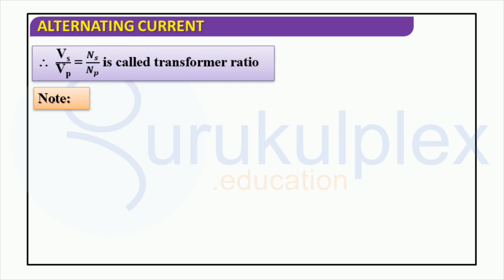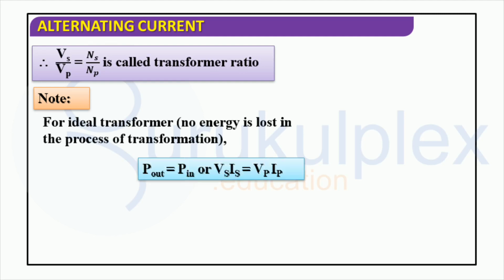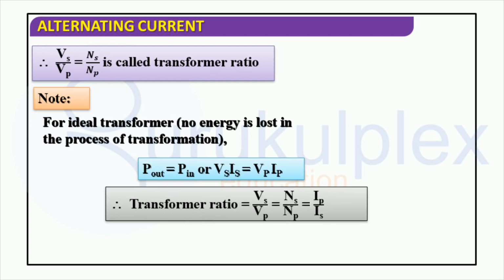This is why AC is needed for this process, since ideal transformers cannot be used with DC voltages, as they are based on Faraday's law. The equation of voltage times current in the secondary must equal voltage times current in the primary must be maintained for an efficient transformation of power from one circuit to the other.